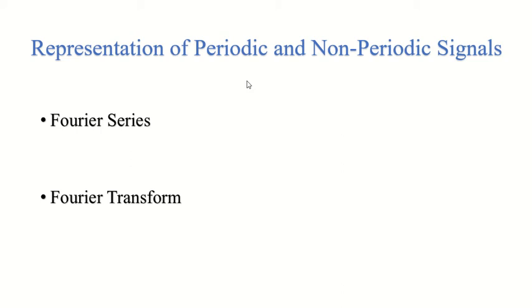So the question is, why Fourier series and why Fourier transform? How does it help us with the analysis of my signal, right? Basically the Fourier series is used to represent any periodic signal in terms of complex exponentials. And these complex exponentials which I'm talking about are called basis functions. They are nothing different, just basic sinusoid functions. And we take three different variables, which we call the Fourier coefficients. So that's your Fourier series.